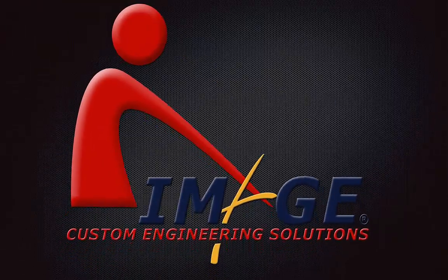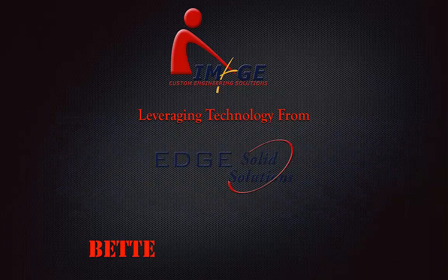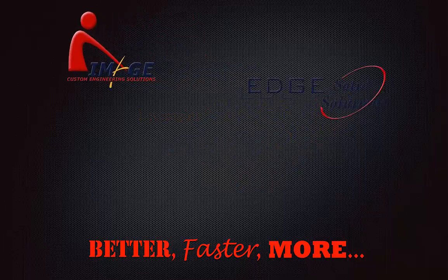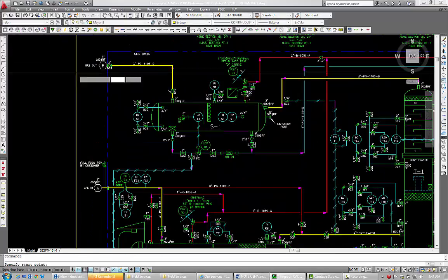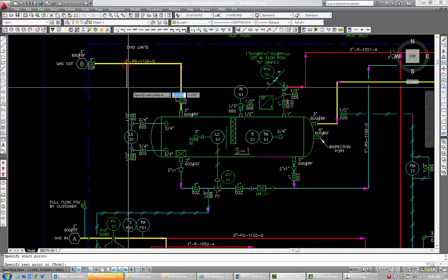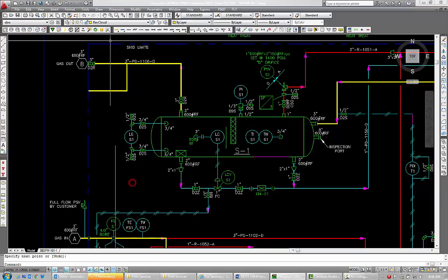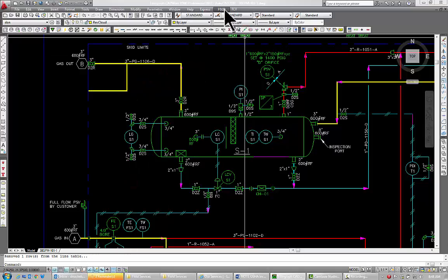In the last video, we entered some marked up P&IDs into EDGE 360. This video shows the process of picking up those marks in real time using CADWorx and P&ID EDGE. Okay, the first step is we redraw a new line in, or add a new line to this existing line. So using CADWorx P&ID Professional, we place the line quite quickly. Then using this to combine line, that merges it with the existing line, the 3-inch PG 1106.